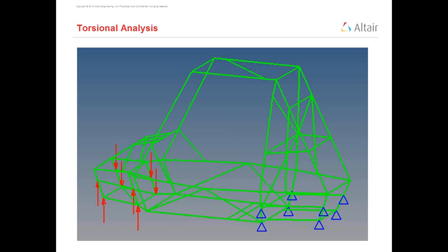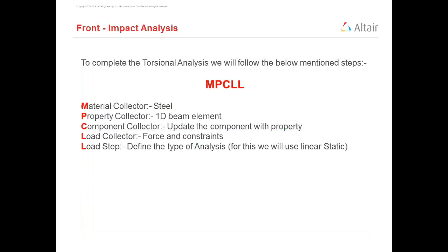We can also perform a torsional analysis in front and rear end both. So for this I am going to perform for front end. In the similar way you can constrain the front end and apply the equal and opposite force at the rear end. So in this way you can perform the torsional analysis on rear end also.